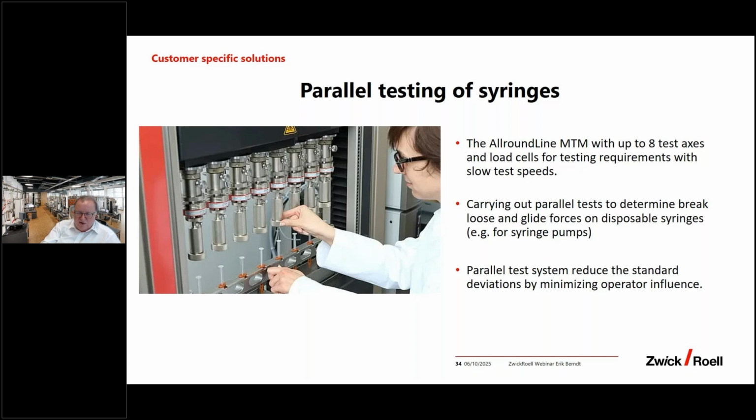And this is a very effective approach for tests that take a long time, like syringe pumps widely used in hospitals. These are run at very slow speeds to simulate the actual usage of the pumps. And this parallel testing dramatically reduces testing times and eliminates potential operator influence.